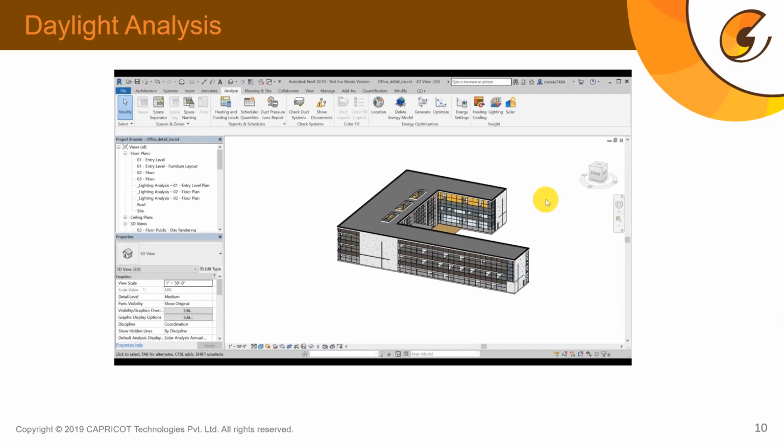Let's suppose we want to achieve a lux level of 250 lux in that space, and we are able to get a value of something around 100 lux from daylight, then definitely we only need 150 lux from artificial lighting. So that decreases the amount of energy that we are going to use through electricity. So that plays a very important part. And then we can take a decision of whether we want to increase the daylight or decrease the daylight. So I'll show you this slide.